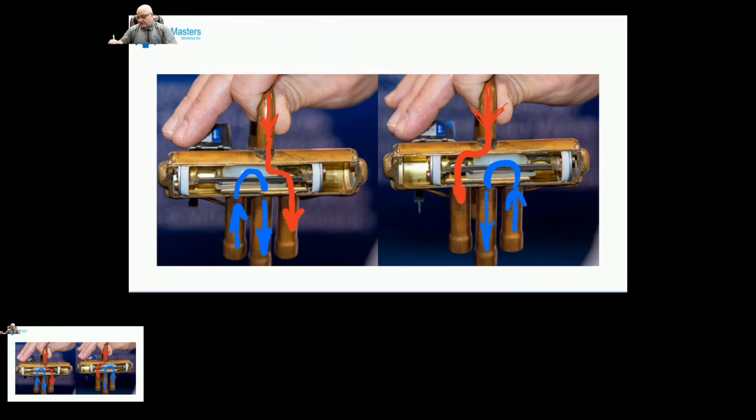notice is, okay, so you probably don't notice it here, but you should remember that the pressure of the system is filling this here. So the pressure of the system is pushing that armature inside that cylinder, left and right, depending on which side the pressure is directed.